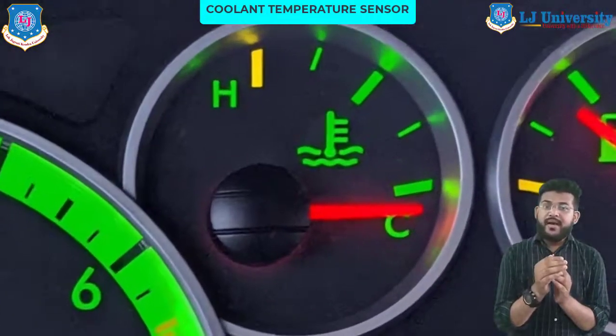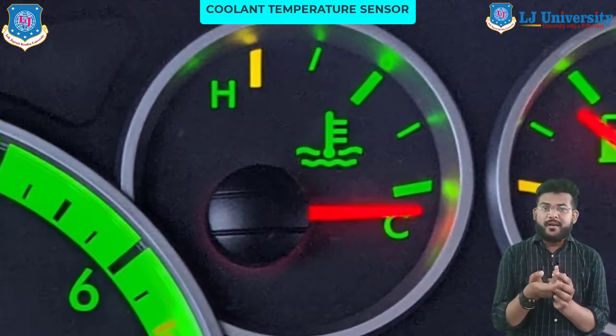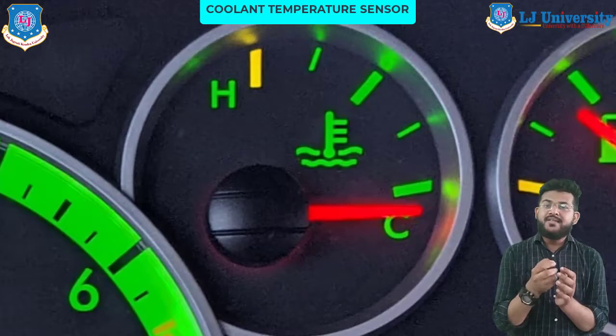So if you see that the engine temperature symbol C is lighted continuously, does not disappear even after some time, it indicates that there is some problem in the engine cooling system. Also the engine temperature goes above the prescribed levels, almost above 100 degrees centigrade.